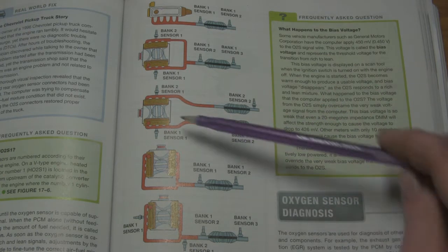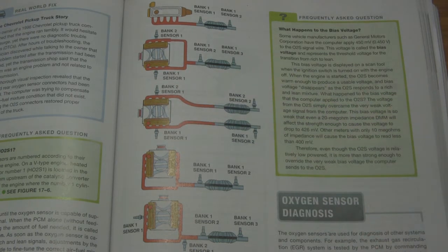So now we can fine tune one bank off the other in case, let's say we had a misfire on bank 1. Let's call bank 1 the driver's side. So hypothetically, if we had a misfire on cylinder 1 on bank 1, in the old version, if the entire engine were on 1 bank by itself, all of those fuel trims would be adjusted.